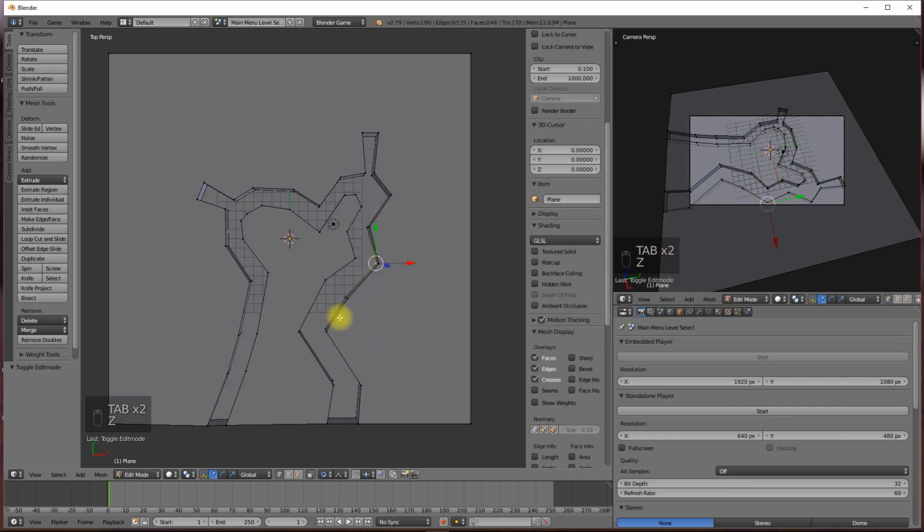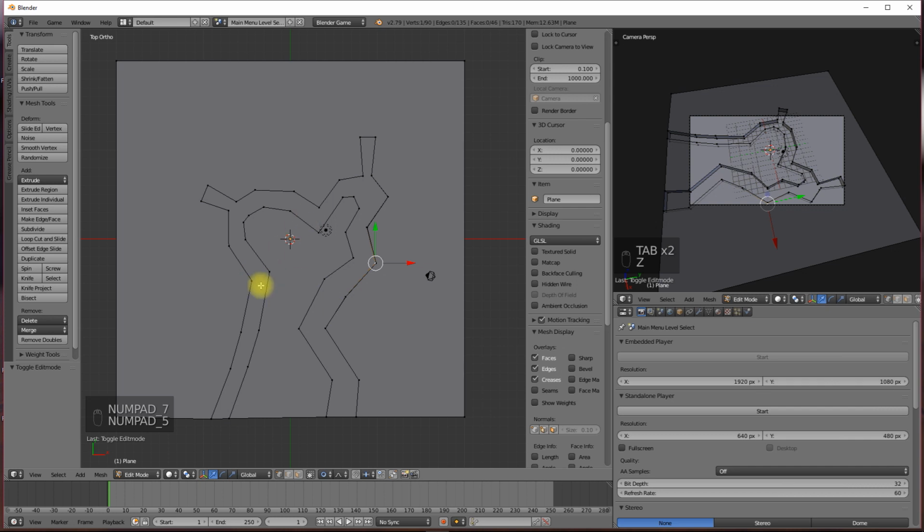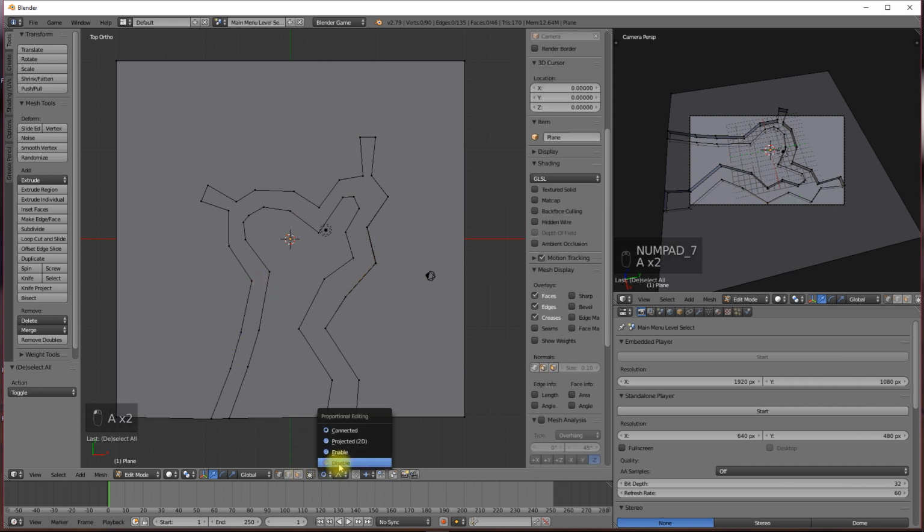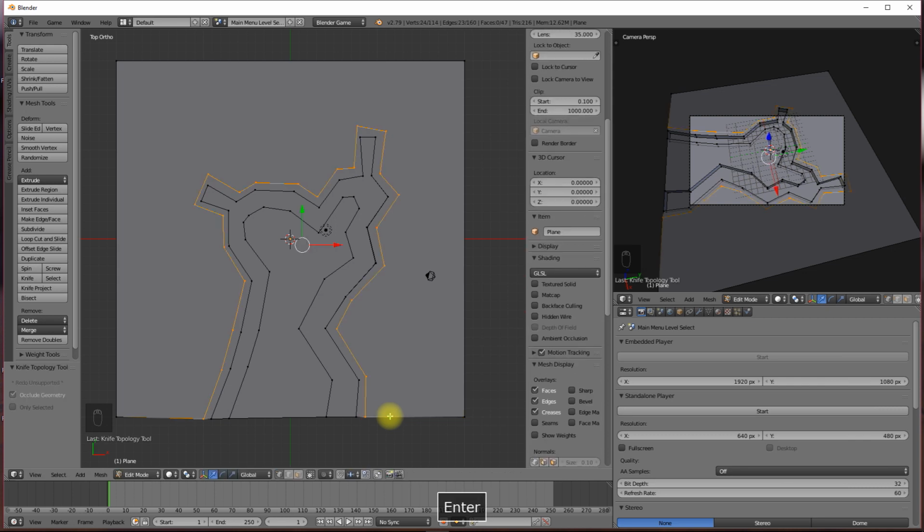Next thing I'm going to do is make a curb. So I turn off proportional editing, go back to my knife tool, and again I'm just trying to emulate or follow my previous outline. Now it will try to snap me to the faces, and I don't want that. I want to keep a little distance in between, and again this is so far from physically accurate that it's hilarious. So we'll go all the way around the outside, and we'll go as far as here, and when we're happy that we're there we'll hit the enter key and we'll have completed the cut.